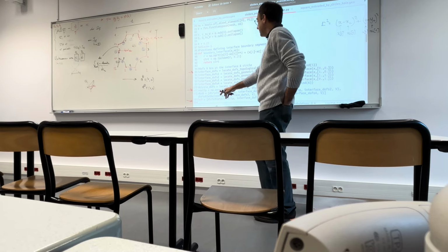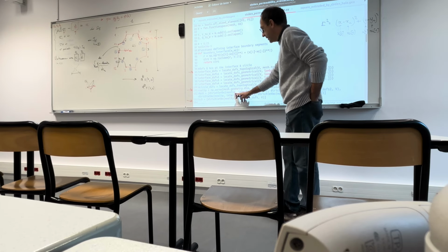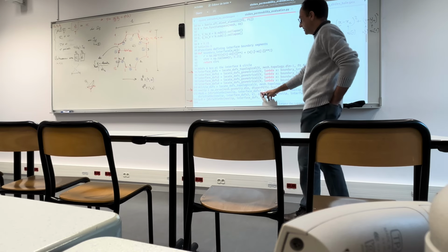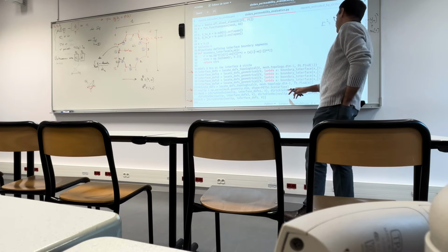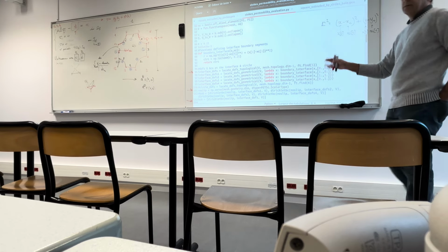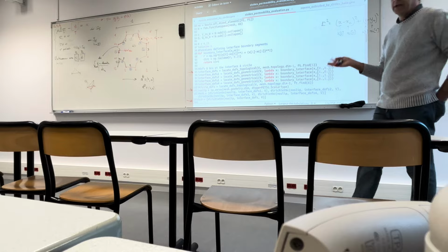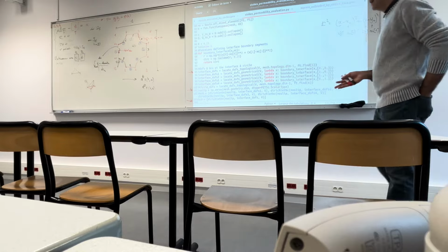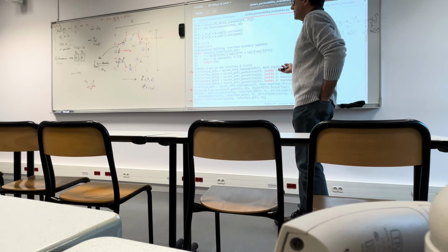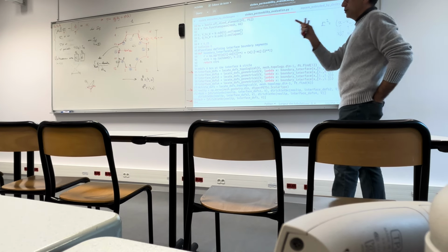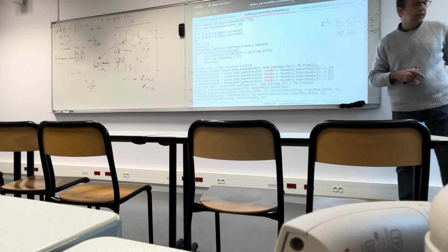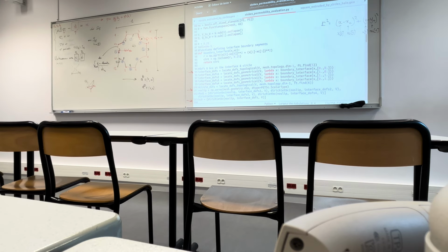BC naught would have been the Dirichlet boundary condition of no slip kind, so the same kind of assignment, on interface DOFs 1 on V, then the same for DOFs 2, DOFs 3, and DOFs 4. So either the first or the second, these are equivalent assignments. Okay, so we are specifying 0 Dirichlet boundary condition on the fifth part of the boundary.